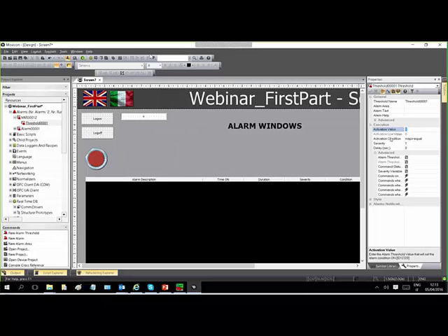If you want a fast refresh, you can insert a lower number of alarms. You can connect through this object also to an OPC AE server. If your system is sharing the OPC, you can browse an OPC from here and connect the object. You can add and change the font from here, and then you have the classical properties of the object. This could be one example.